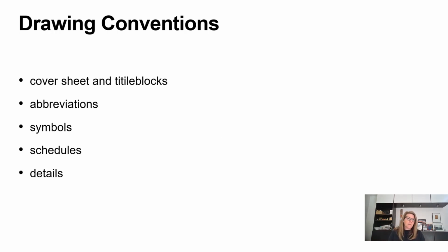Outside of just those sheets, typically there's a cover sheet, and that will have those that are part of the construction process. It typically will indicate the owner, the architect, the engineers. It will identify what building codes are being followed in that set of documents, whether that's on the cover sheet or on the next information sheet.